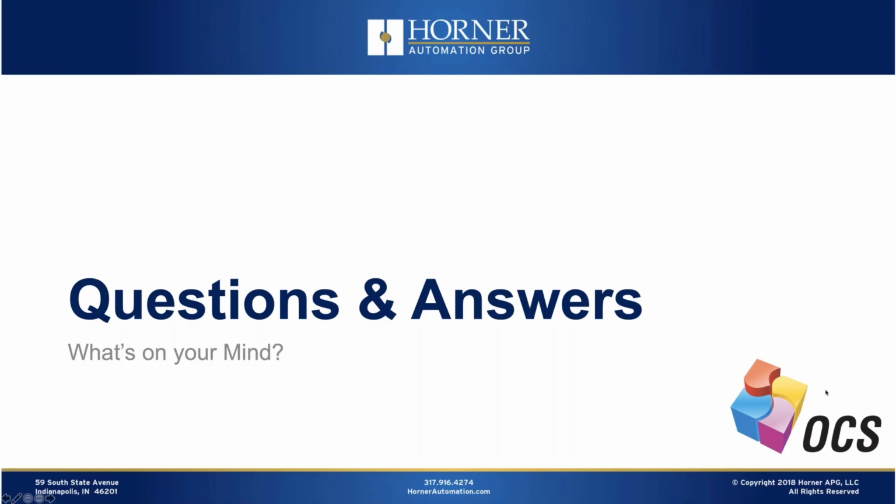Let's see. You mentioned the Q clear bit is for non-sensitive clearing. What is the best way for clearing a totalizer if it is time sensitive? Well, that would be from an external input. So you would effectively configure your clear input, and the same argument can be used for preload as well as disable, etc. For those that are super time sensitive, you're going to want those to come in through an external physical input, because those physical inputs are wired directly into the high-speed FPGA chip and are not impacted by logic scan. So in that scenario, you're going to want to use some sort of external signal that you can wire in that way.